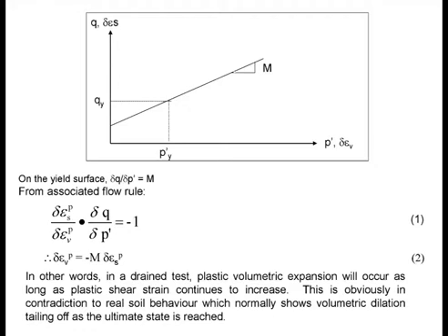Okay? Now, if the soil specimen, a triaxial specimen, is allowed to expand, then all it will do is keep expanding. So your volumetric strain will be a very, very large negative number. That's basically what will happen. But in the undrained analysis, the question will be asked: in the undrained situation, there's no volumetric change. So what happened to this volumetric strain? Because the soil is trying to expand, right? But on the other hand, we say, sorry, you can't expand. And then what happened? This is how it is worked out mathematically.